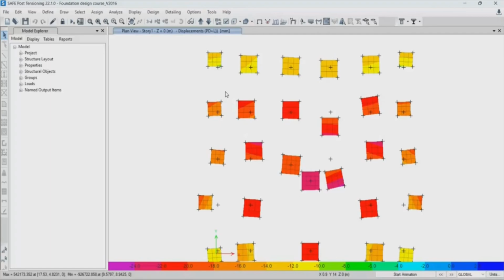Okay, so if your footing is not thick enough, let's say you have a footing thickness of 200 millimeter, the column is going to try to punch through the footing. We don't want such a scenario to occur, because if your column punches through the footing, it is going to lead to failure. So in that case, you have to increase the thickness of your footing so that it passes the punching shear check. So that is the meaning of the punching shear check.